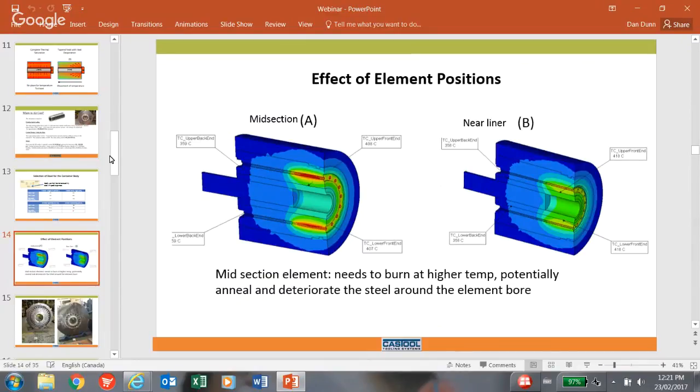holes. In figure B, the heating system, or the QR system, runs substantially less, as the elements run only to balance the heat between what is being generated during extrusion and what is being lost to the surrounding press tooling and press components. This leads to a reduction in energy consumption and the elongation of tooling life.